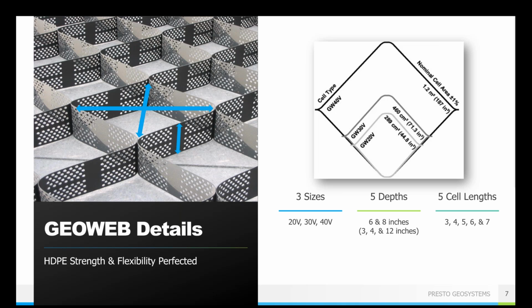Something I do want to point out about geocells specifically is the ultrasonically welded seam. That's where all of the connecting points are, and that's really important to the function of a geocell. The stronger that seam strength, the better the performance the geocell is going to have, period. A strong seam allows for a better overall lifetime performance and steeper and taller slopes.